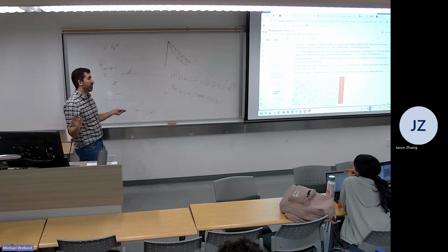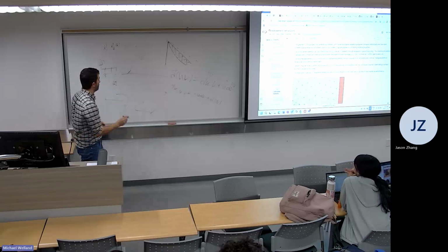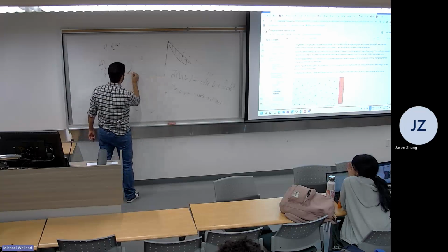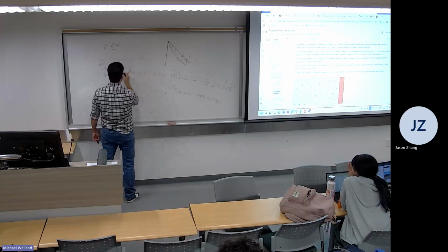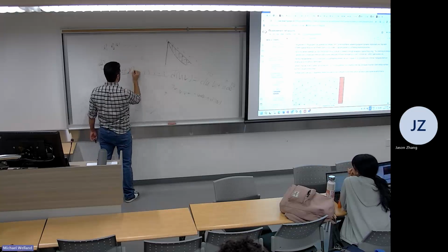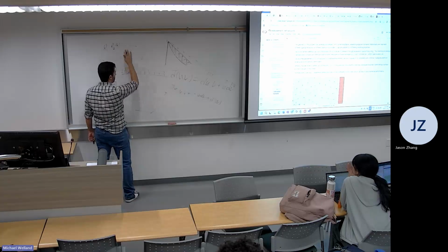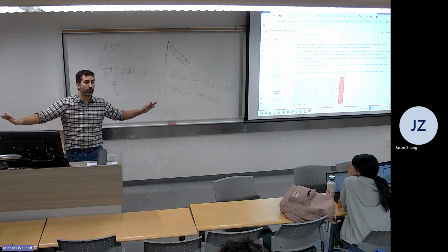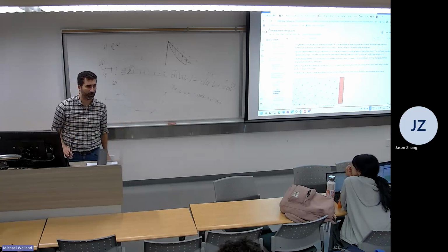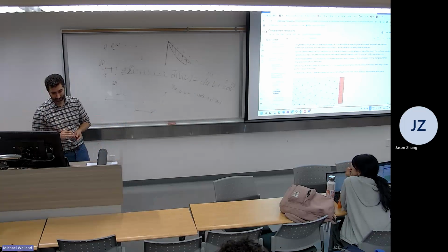Turns out that CFD works really well on rectangular meshes. So what you do is you put up a boundary layer of squares, quadrilaterals, and then you just take over with triangles. Then you make the triangles very big, and you're out into the bulk again. No problem. Doesn't matter. Finite element is perfectly fine with it, which is nice.